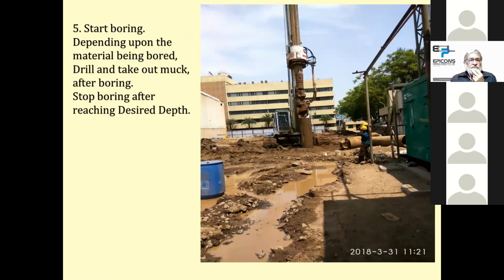Subsequently, start boring, depending upon the material being bored. Drill and take out the muck after boring. The depth of the boring is normally measured for every 10 minutes, and the boring depth is registered or noted down. Stop boring after reaching the desired depth.